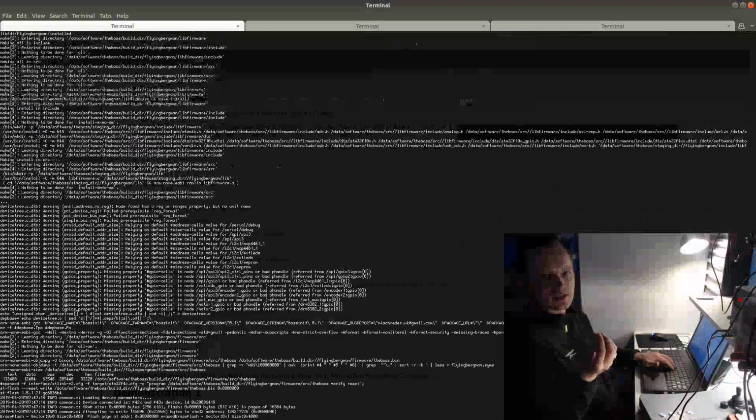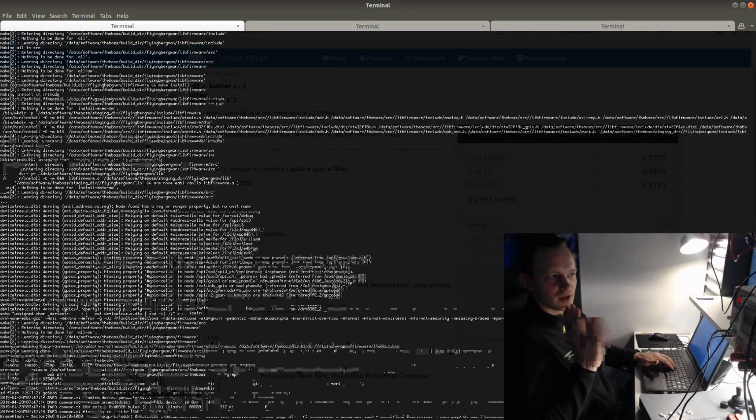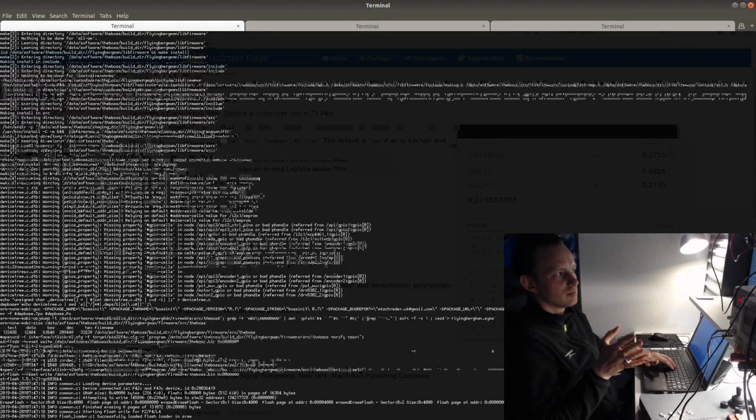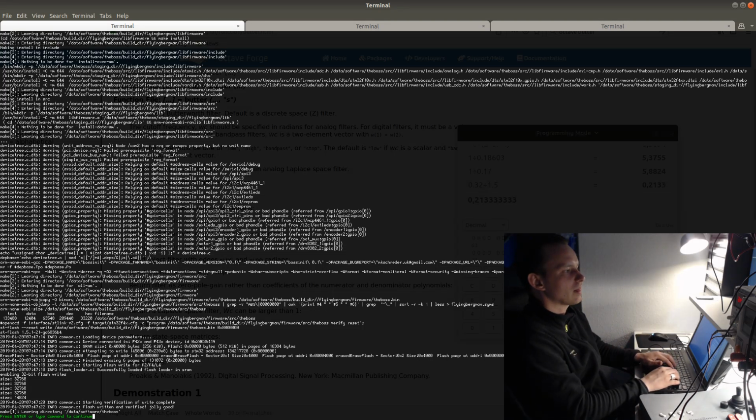So basically 0 means there is no repetition counter. It's going to fire on every single event, so both the high and the low. 1 means that it's going to fire on every second event, which would be, if it starts on high, then it will fire on the low event. So it will only fire on low events. And setting it higher will just make the update event fire at a much lower frequency.